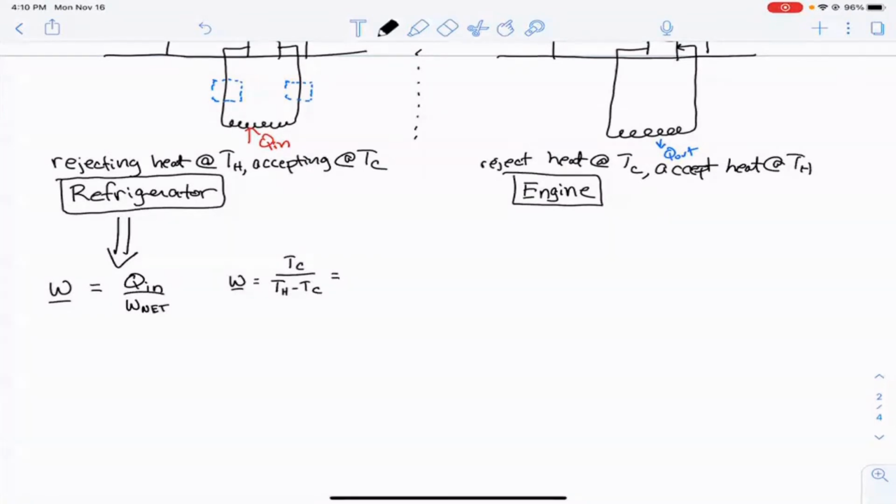And so here we know that the cold temperature is 15 degrees C, right? Or the cold reservoir is at 15 degrees C. So that's 288.15 Kelvin divided by then 298.15, right? Because the hot temperature is the room temperature, then divided by 288.15 Kelvin. So our coefficient of performance then is equal to 28.8. And as we talked about in the last lecture, of course, that's to be expected that the coefficient of performance is greater than 1. Now, 28.8 is very high and artificially high. But then again, the Carnot refrigerator is the best that we could ever do.